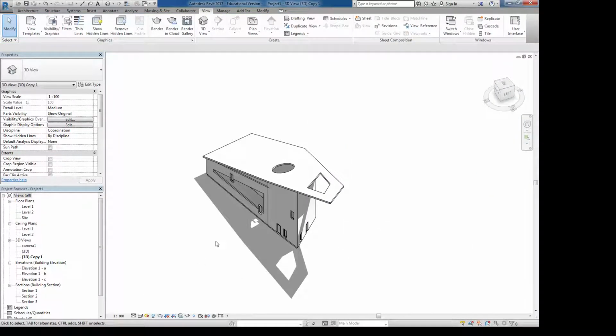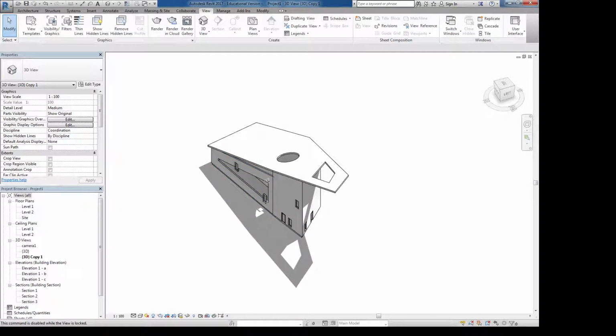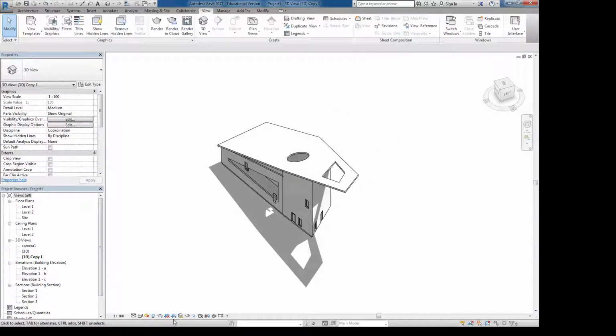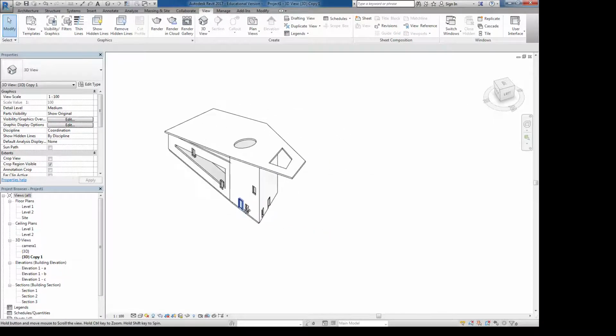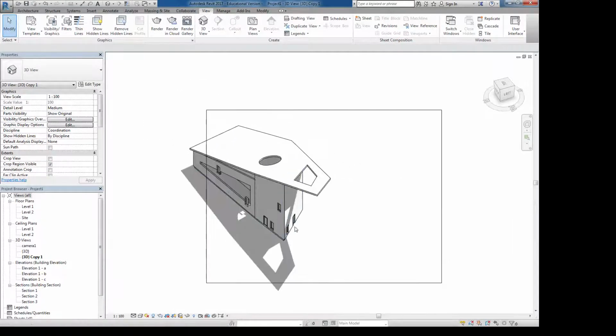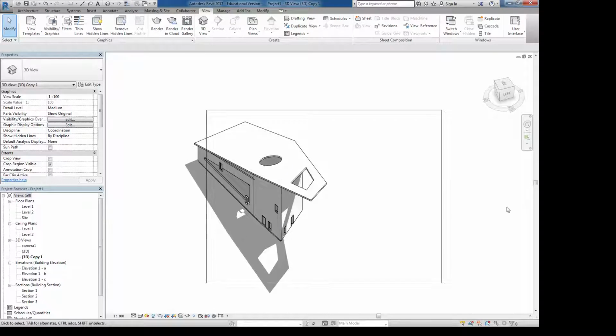Okay, so the way to avoid that is to click on this unlock 3D view or lock 3D view, and then if you do this, you can save the situation of this view, and then your view will be saved. So I can't orbit around anymore. The angle is fixed. I still can snap or pan around, which doesn't make any changes because if my region is fixed, my region is moving with me, so that's not changing my view. But I can't orbit around because I've locked the view, so your camera is saved. And you can always unlock it and then go back.